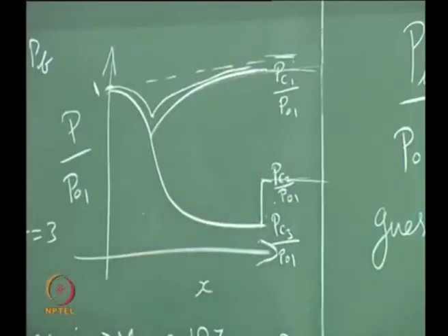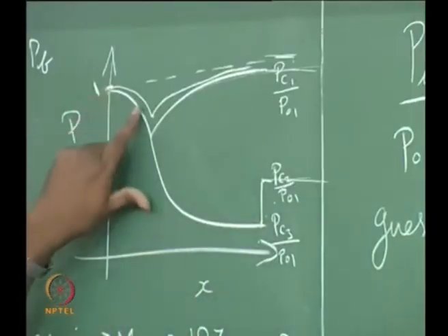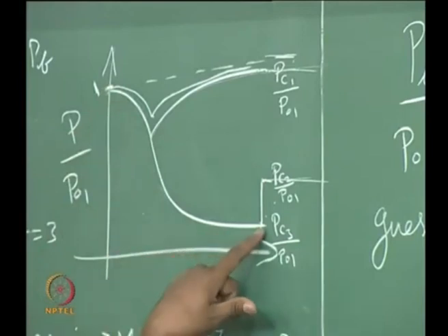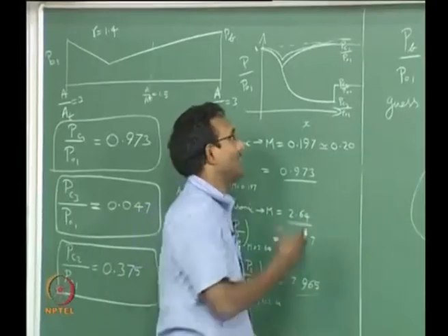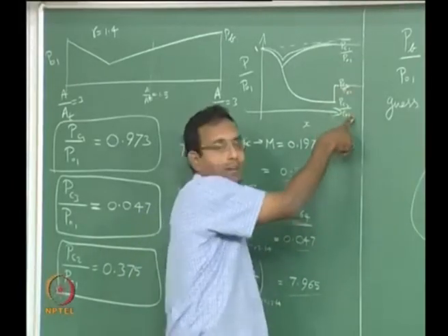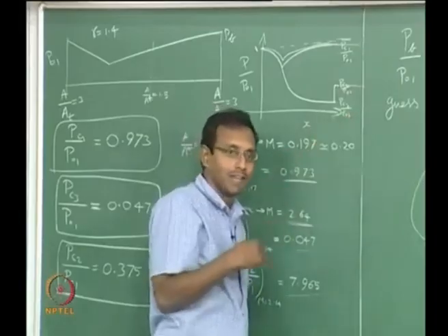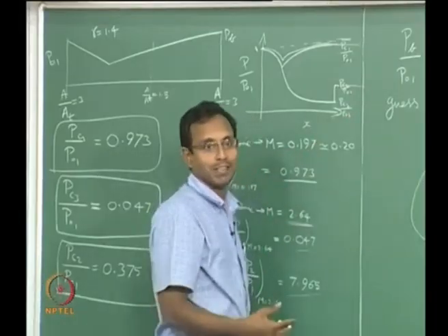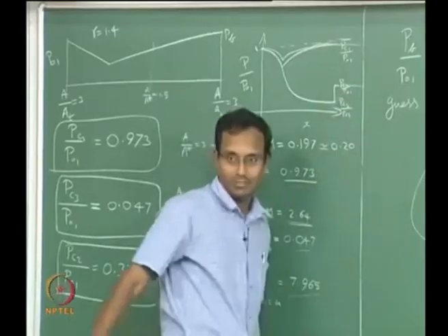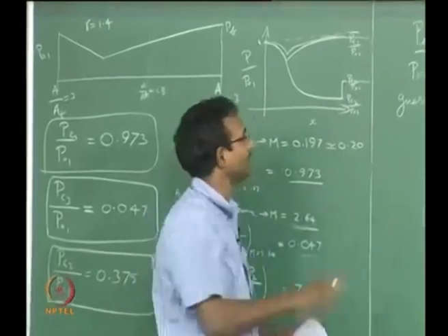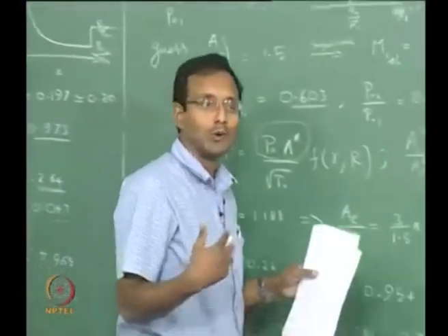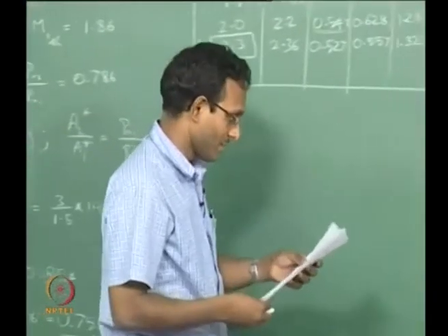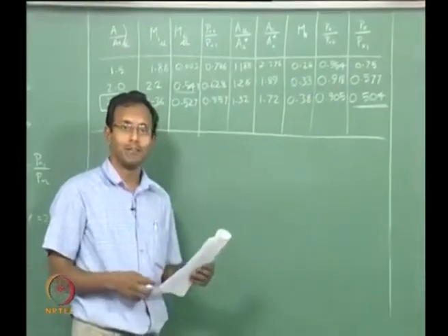It so happens that for all those cases, inside the duct it is exactly the same pressure profile. So I will solve the same thing as P critical 3 and it will be the same everywhere inside the duct. Ideally the remaining portions, over expanded and under expanded, I have to talk about after I introduce jets to you guys, because only outside the nozzle things will change. Inside the nozzle it's exactly the same as the critical pressure 3 condition. If you know that, you know how to solve the problem now. Now I'll give a more complex problem.